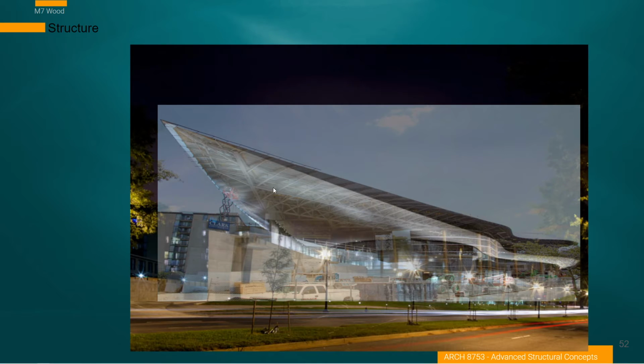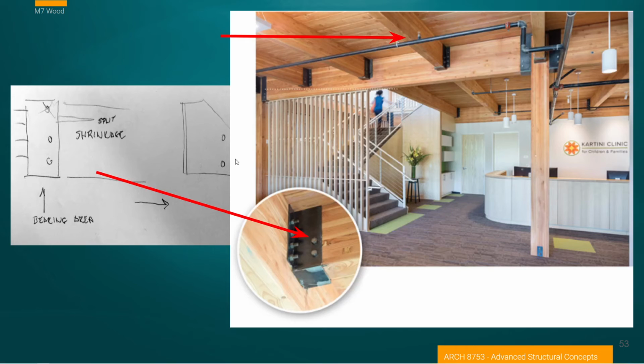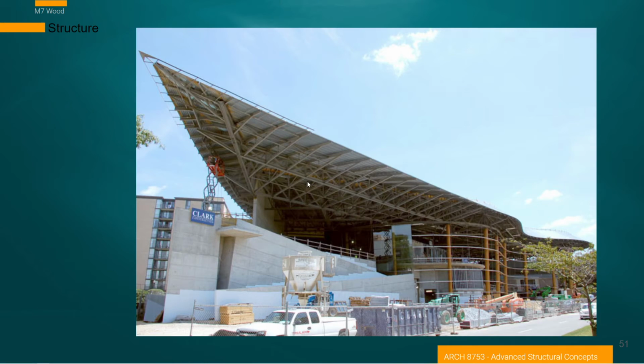This is not really a hugely successful attempt at that, but it really does show you, if we go back and look at the structure here, how we get to these very thin looking exterior end conditions of roof systems. So we have these massive truss systems coming out, this one coming off of even a concrete wall, a massive truss tapering down to zero because the loads are going down to almost virtually nil at the end of the assembly.